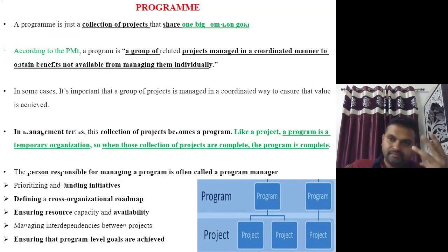Let's try to understand what managed overall means with a very simple example. Of the three projects in the same city, one project is in the excavation stage, where only excavation activity is going on. In another project, the complete building RCC has been done and finishing work is going on. The third project is about 50% done. The project in the excavation stage, as soon as it goes above ground level, will require more formwork, because the main RCC work starts above the plinth level.